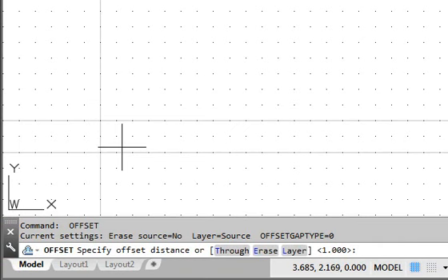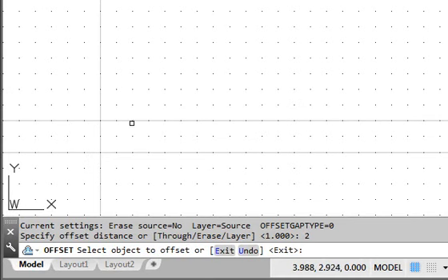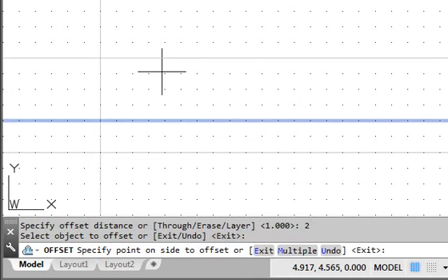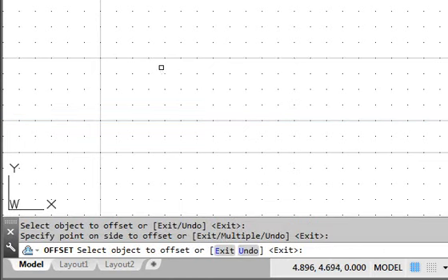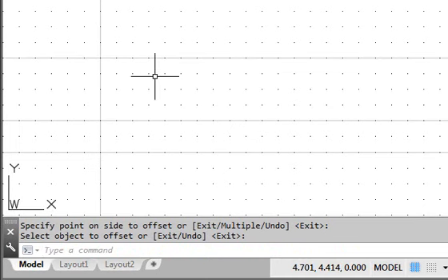The height of the design is 2. Pick the top horizontal line and place an offset line above the selected line. This new line will be used to define the beginning of the top view region. We will continue to add more construction lines to define the regions for the 3 views.